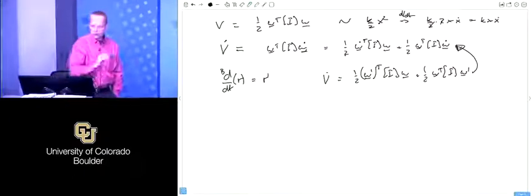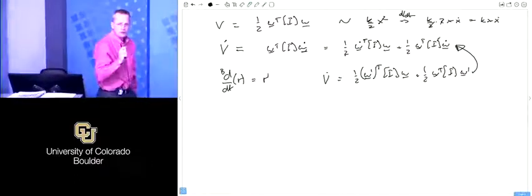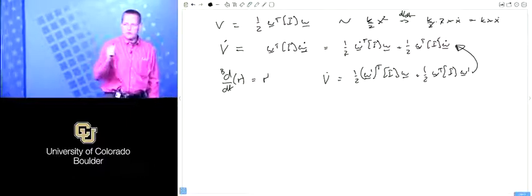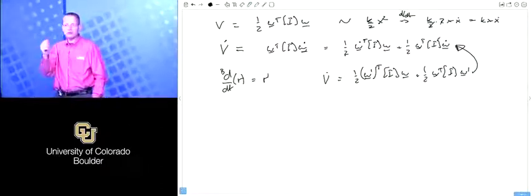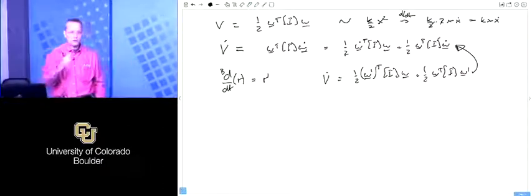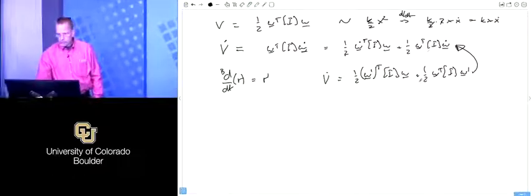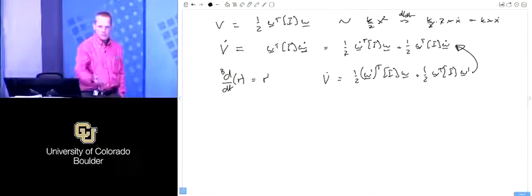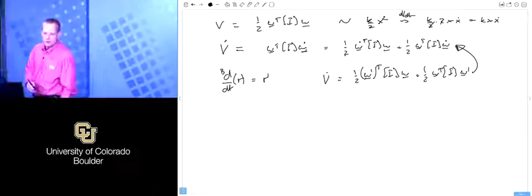But just if you're doing this trick and you're going from here to here and putting dots everywhere, be bloody careful that you understand what you're doing, right? Because if you're really taking inertial derivatives on everything, if you have a tracking problem, this is omega b relative to r, and you're just adding dots on this, what are you really taking? If you're not sure, do this stuff first, and always pick the frame that keeps the inertial tensor fixed. Otherwise, things get really crazy, typically, right? Then you can do that.